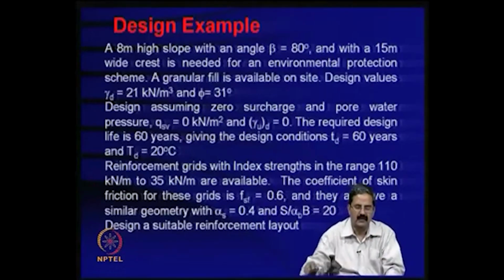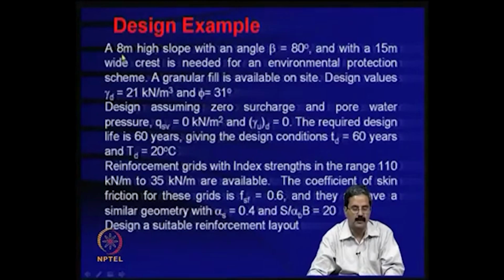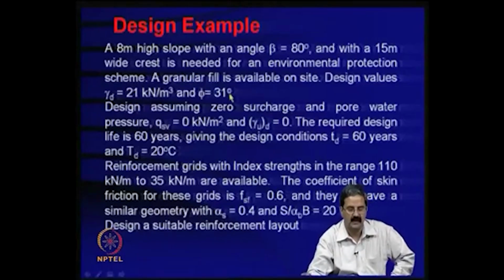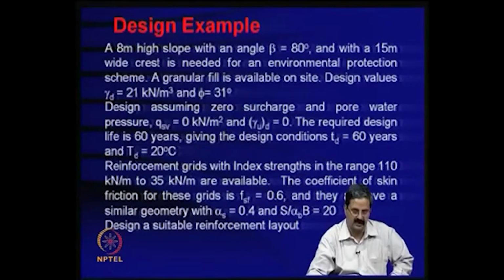So, when you have a surcharge, you assume that it is only 8 meter slope, but design it for 8 plus 1.1, okay. That surcharge effect is considered, okay, and like that. So, design in this case example I am just only illustrating, but suppose you have a problem with surcharge, particularly when you are trying to design using IRC and other guidelines, you need to know how do you handle surcharge, okay. The required design life is 60 years, okay.